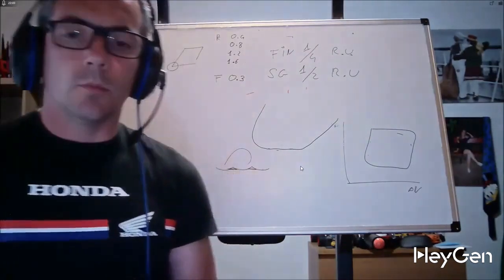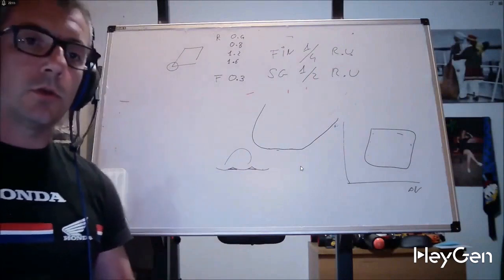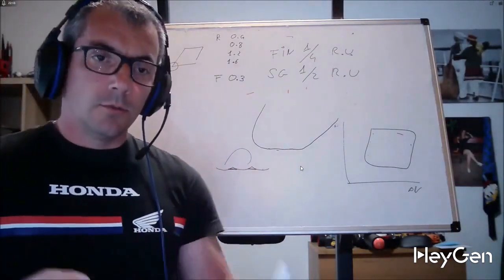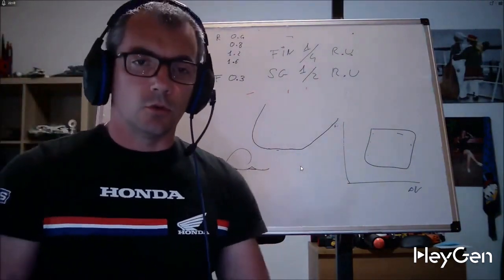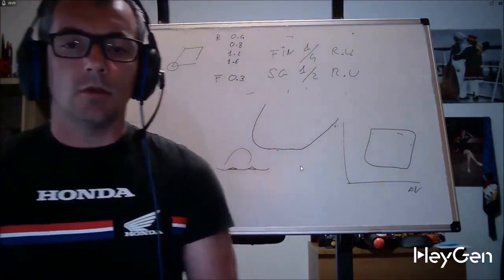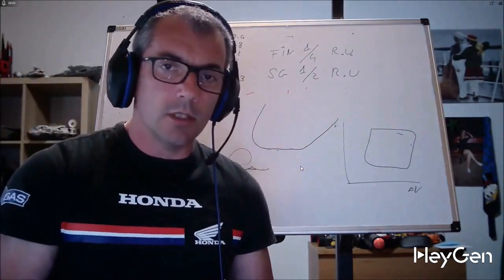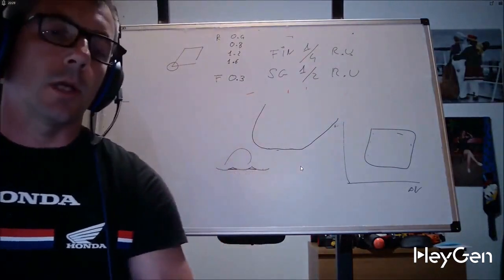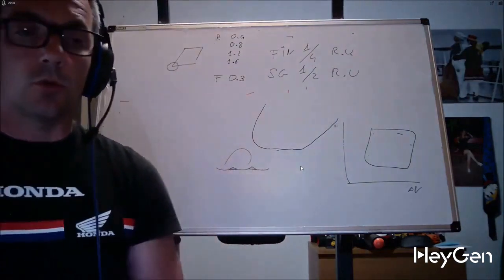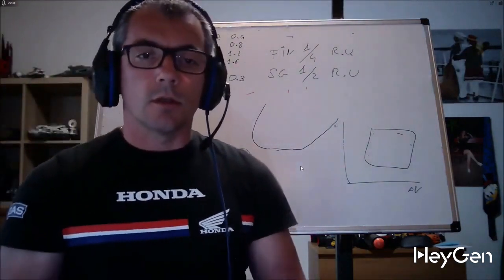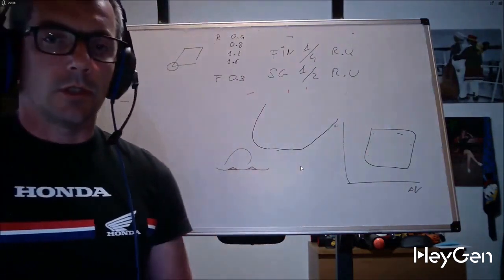Okay. Well, so we have seen some importance of knowing the shapes of the tools. So, programming. Based on the tools we have, or in the drawer, that we can purchase or that are available on the market. We have some tips on how to manage advancements. So if we work with a radius of 0.4, we never work with an f0.4. If we work with a radius of 1.6, an f0.4 can make sense, even 0.5 or 0.6 in roughing, and so on.